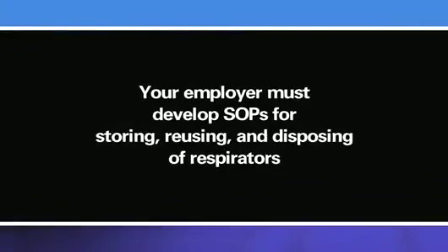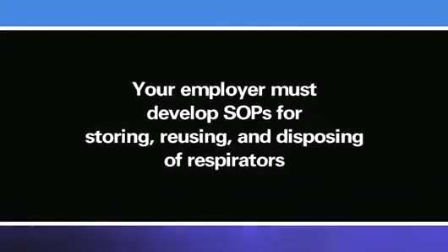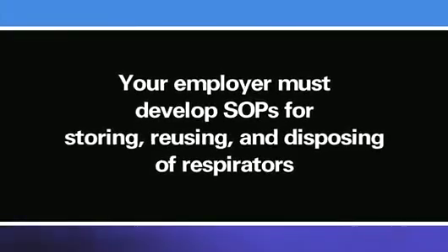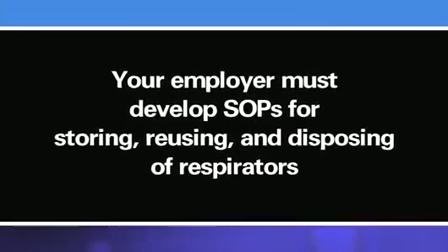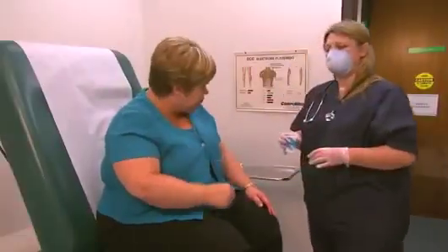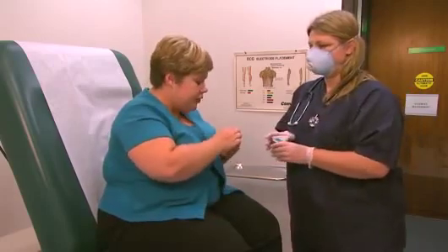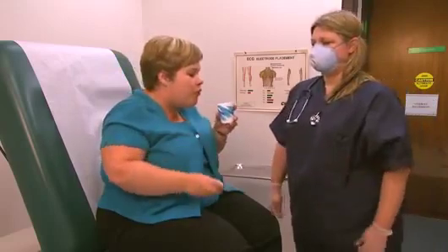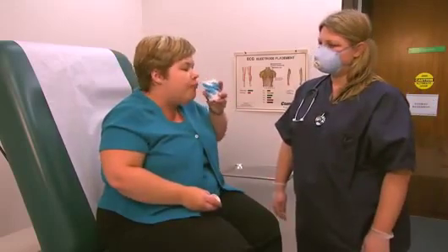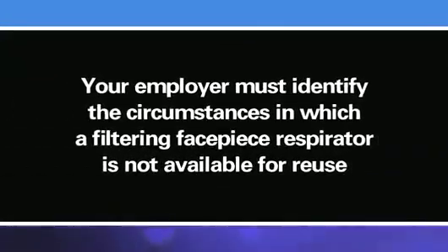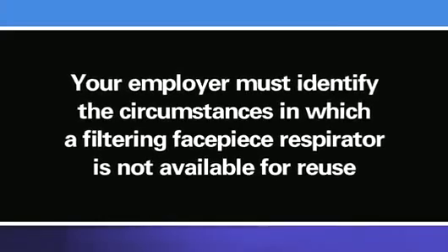Remember, your employer must develop standard operating procedures for storing, reusing, and disposing of respirators that have been designated as disposable. The same is true for respirators with replaceable filter elements. Of course, there may be other reasons for disposing of a filtering facepiece respirator that still appears to be functional. For example, sometimes infection control procedures may require that a respirator be used only once. Your employer must identify the circumstances in which a filtering facepiece respirator will be considered to be contaminated and not available for reuse.